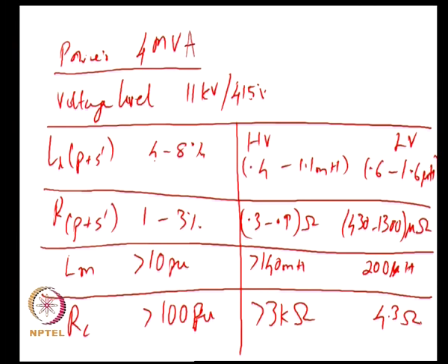You might actually make use of the physical units in your actual design procedure, but to convey it in a more general manner, the percentage or the per unit is a good way of doing it. Again, if you look at say the magnetizing inductance, if someone says the magnetizing inductance is just 2 per unit, you can immediately say that that transformer draws a lot of magnetizing reactive vars, because that would correspond to 50% of its rating being its no load vars.